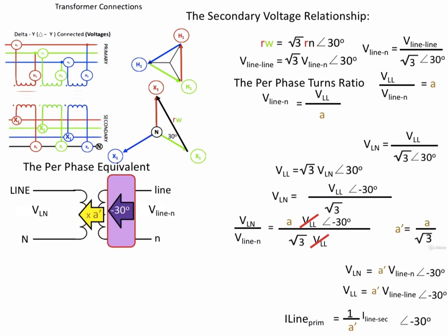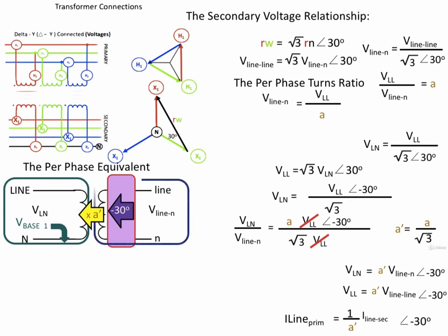So now I'd like to establish the per unit equivalent circuit. And establishing the per unit equivalent circuit, of course, we have to pick our two base voltages. And the two base voltages are determined by the turns ratio of the transformer. And I've outlined them there in zones with the green and the blue box.